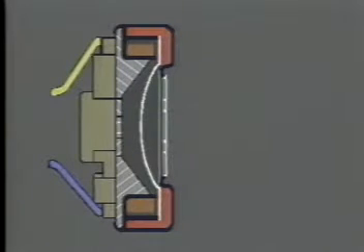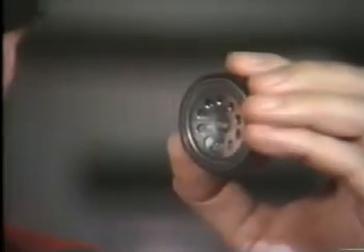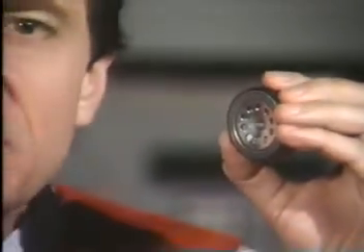The electromagnet, when energized with electrical current, will then vibrate the diaphragm about this biased position by merely increasing or decreasing the pull already exerted on it. This approach not only increases the amplitude of vibration, it also prevents the diaphragm from vibrating too often, eliminating what's called frequency doubling. Let's illustrate the entire concept.